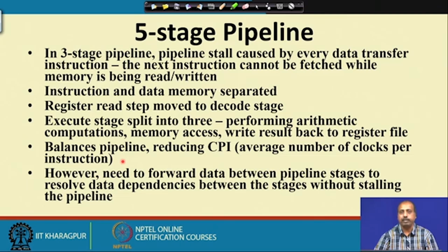So, in a pipeline fashion, a number of instructions are executed in a pipelined way, so you can execute more instructions. Ideally we would like to have 1 clock per instruction, because if I have one instruction taking 10 stages and the architecture is a 10 stage pipelined architecture, then after every clock cycle one instruction should be complete.